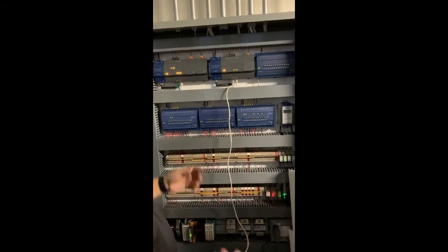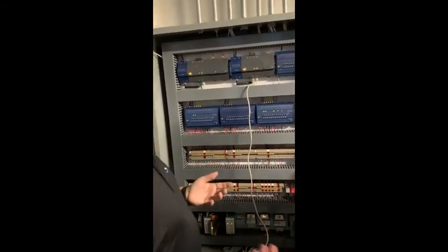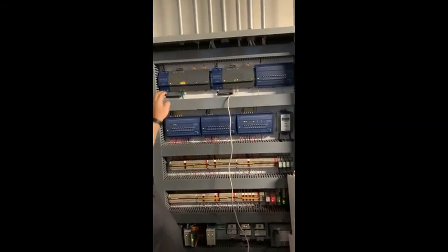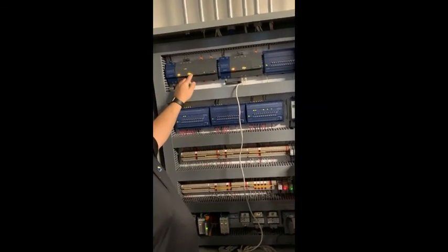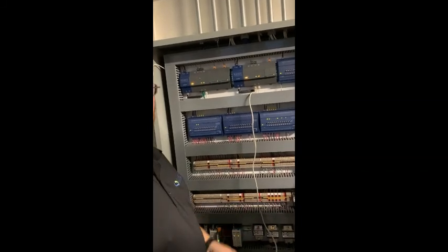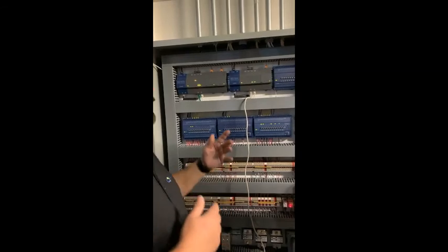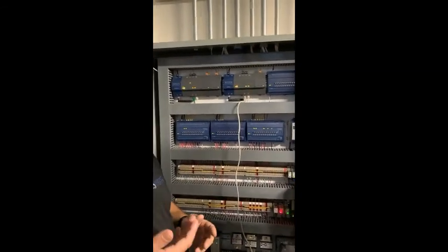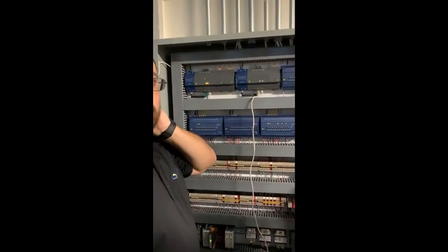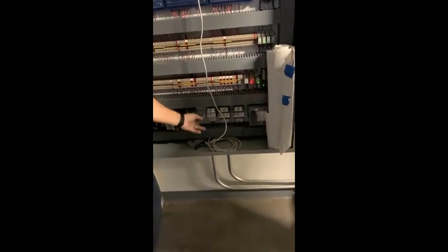So if you came down here and these lights are off, it might not have power. If it does have power and these lights are off, that means the Jace has failed. If you come on power and these lights aren't on, or they're on and you're not getting any blinking, that means the communication's not working. If none of these lights are on, there's no actual physical connection, so maybe the switch that they go to is disconnected. All the data within the building is on its own local network. We had to order another switch, it's not in yet, that will replace that for a panel mounted switch.